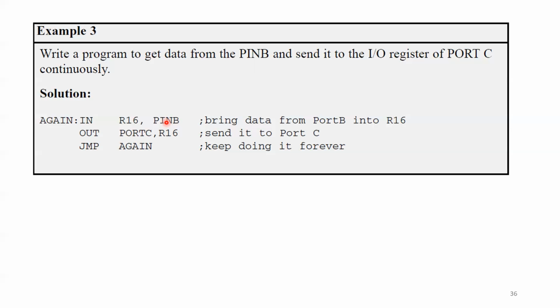Okay, for that we have different syntax or names for the same port depending on whether you use it as input or output. For input we use pin, and for output we use port. But physically, either pin B or port B would be the same port and the same pins in the microcontroller. However, if you are going to use it as input, you should use pin. And if you are going to use it as output, you should use port.